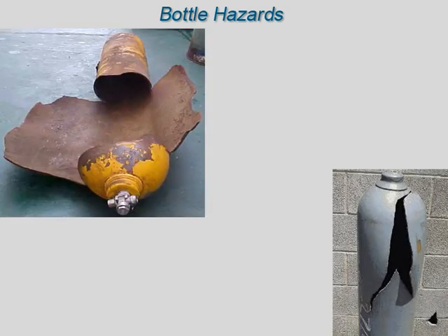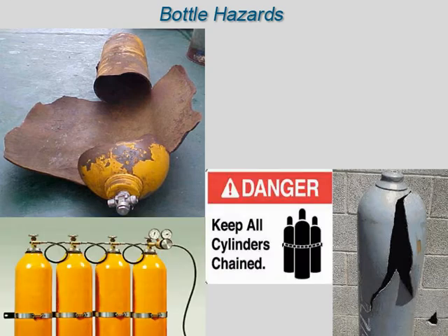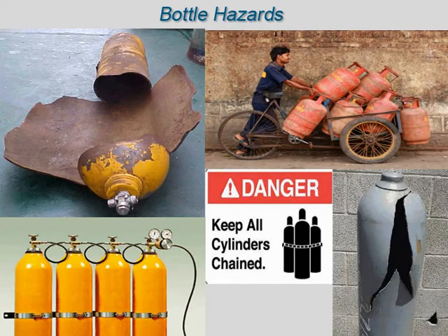Shut the cylinder valve and secure the cap when the cylinder is disconnected. Never lift cylinders by the protective cap. Store bottles upright and always clamp or chain them in place to keep them from falling or being knocked over. Always transport cylinders in secured and appropriate vehicles.